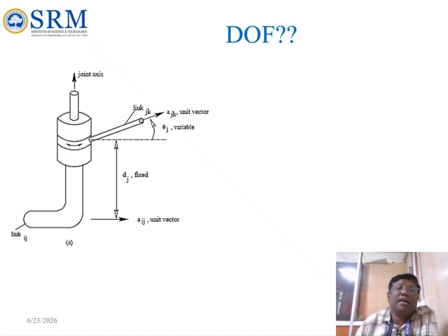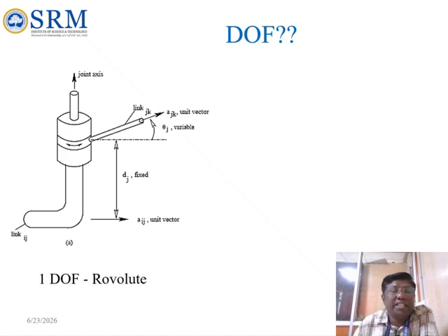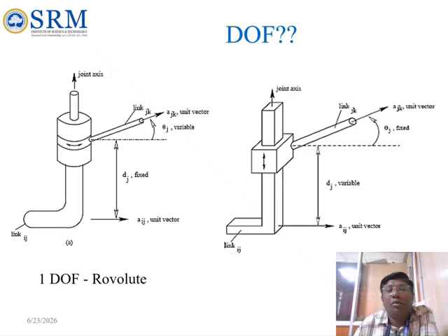And if you look at the degrees of freedom, how the notation can be given. The link between this is called a d_j, and this is the link that is given as j_k. A of jk is a unit vector, the angle of how it is rotating about the joint axis. So 1 degree of freedom means it is a revolute joint. If you look here, this is the revolute joint, 1 degree of freedom, it is rotating. Then here is a prismatic joint, where we have this movement in the prismatic joint. Okay, prismatic joint.